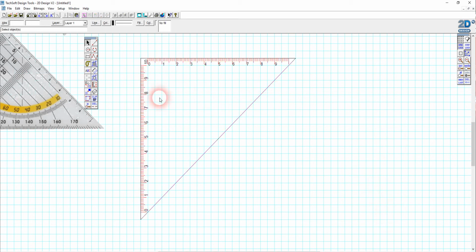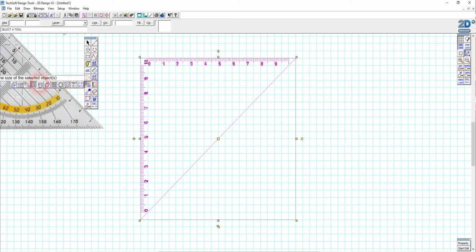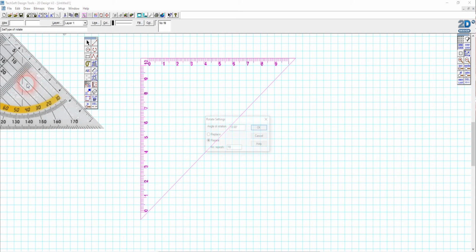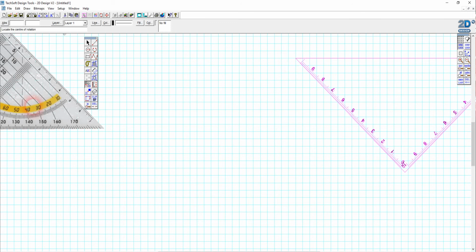Okay, with it selected, I'm going to come to the transform tool here, and choose from this list of transformations the rotate the selected objects. The text has gone off the screen there, but it says rotate the selected objects. I'm going to rotate this to that 135 degrees that I was just looking at. This is always anti-clockwise. I want to replace the original image here, and here's the magic. Oh, I've still got radial lock turned on. Turn that off. I'm going to click with grid lock turned on right on this corner here, which means that it will rotate it from that point.